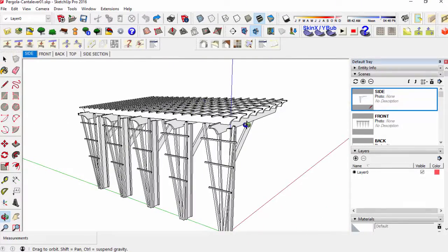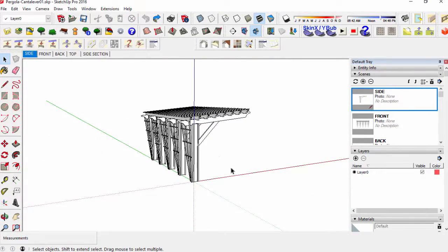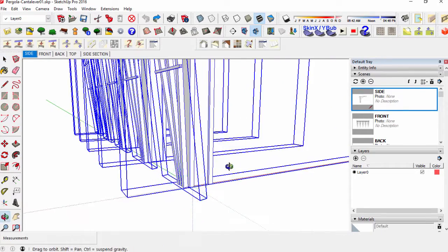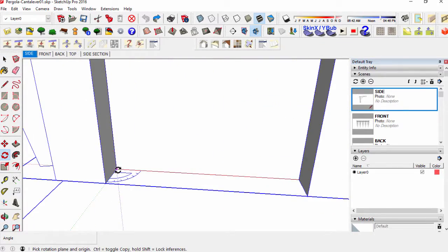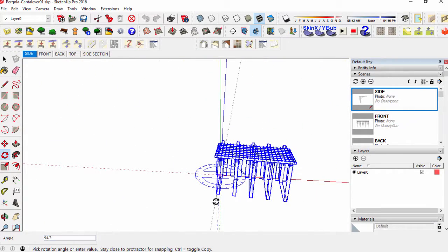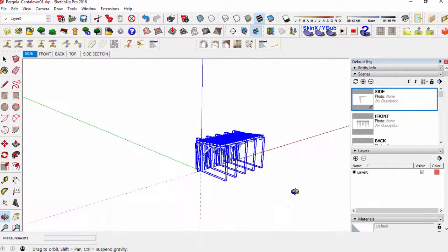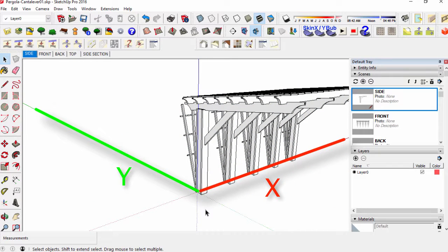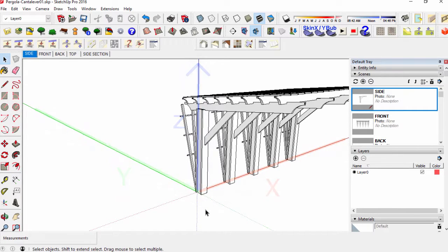Here's an example where I've already created a SketchUp component. I've made sure that the component is moved and rotated so that the SketchUp origin is located at an appropriate spot, which will be the same as my AutoCAD block insertion point. Double check the component's rotation around the red and green axis at this point, and also make sure that the solid blue axis is pointing up.